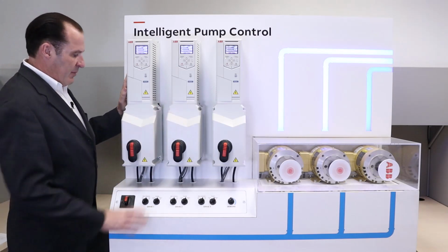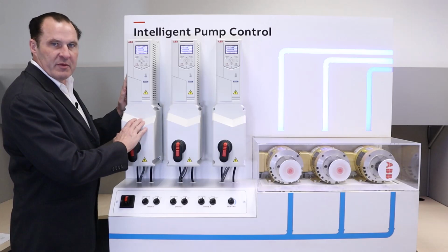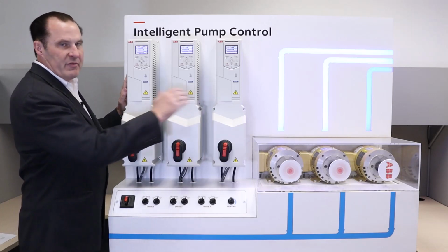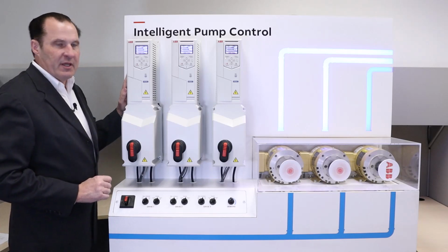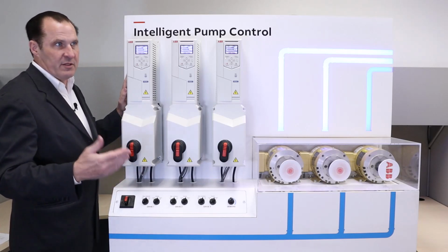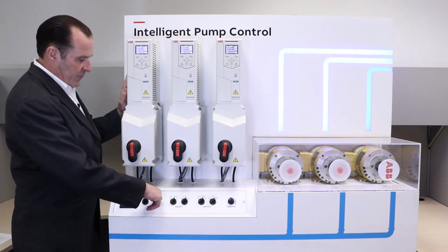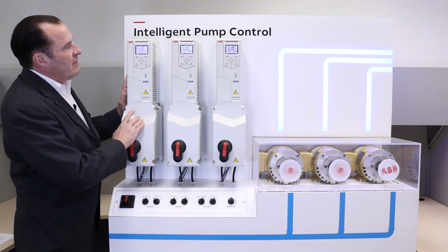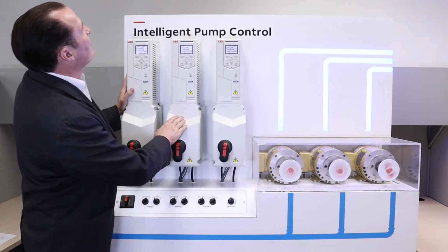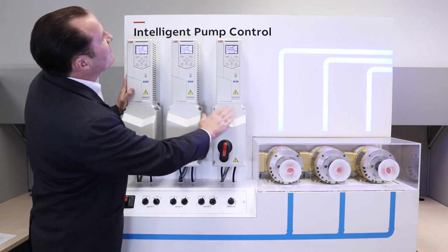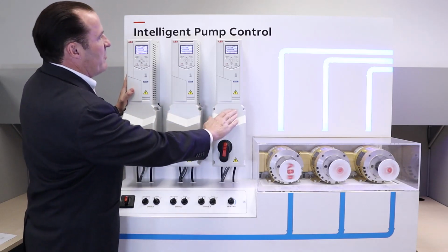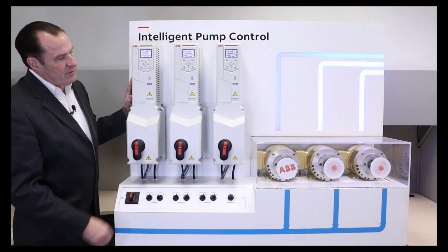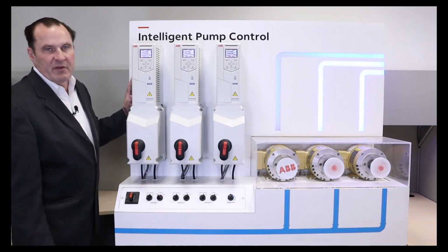I am going to fault the master drive, and with the moving master strategy, drive 2 or drive 3 will pick up the master position. It depends on where in the queue on the system they're at. So I'm going to fault it right now. I'm faulting drive 1. I've faulted drive 1. It's now faulted. And when I look here, drive 2 is follower, and drive 3 has become the master. So the master drive has moved over to drive 3. As we look at the motors, drive 1 is stopped, and drives 2 and 3 have picked up the work.